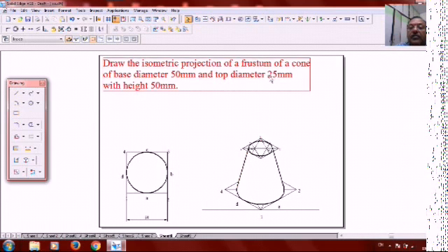When it is say 40 mm instead of 25, then it is 0.8 times 50. Scale 0.8, you will get the required curve. So whenever you do this particular portion, if the top surface is required, don't reconstruct it again. You just lift it, scale it, and you will get the required top.